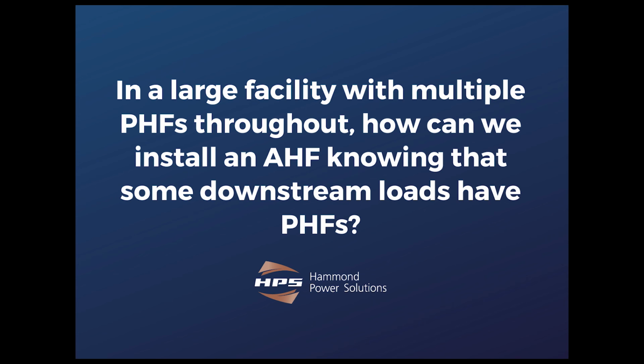But in some cases, maybe if you just need a little bit, and you may have some extra capacity with an active harmonic filter, you may be able to get some additional correction with that, and maybe not even have to provide power factor correction.